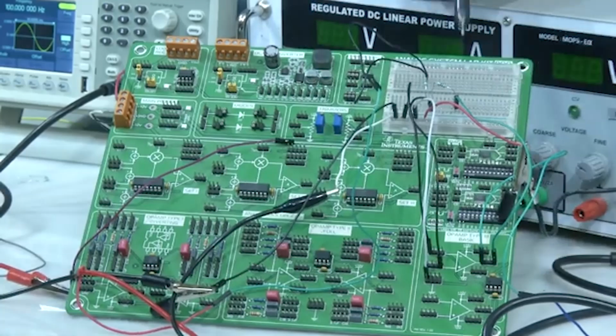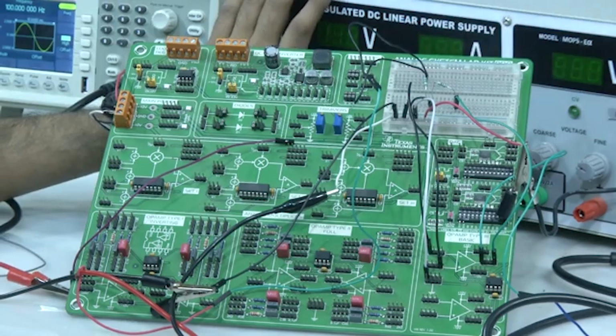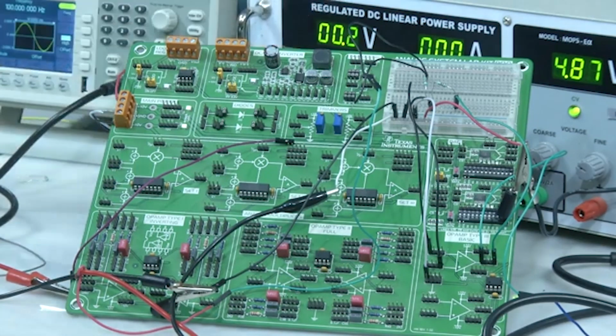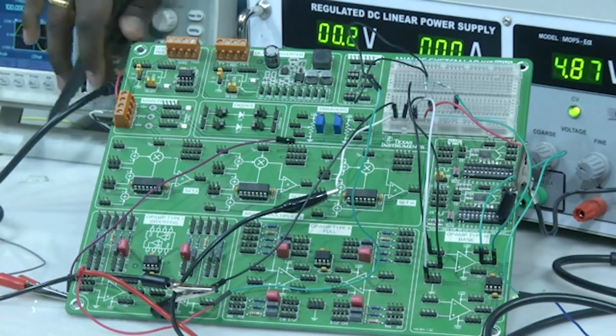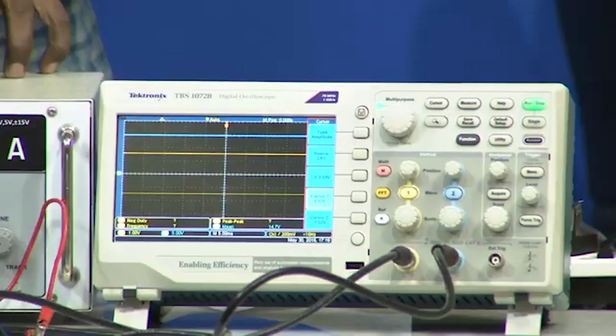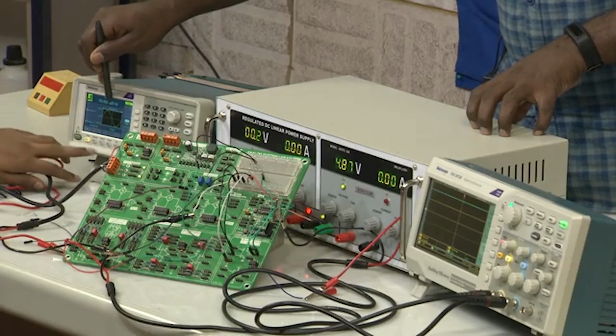Right. So, now we replace the feedback resistor with 2.2 kilo. The remaining circuit remains the same, I am not even changing any point, then switch it on. But what about the input voltage? The input voltage previously we have set, when we look into the function generator, the peak value is 2 volts, right. Yeah, now this value is 2 volts.